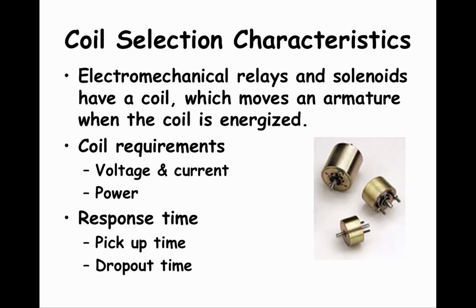Response time describes how much time it takes for the relay to actually respond once the control signal is sent to engage. Again, with electromechanical relays, large ones may have a substantial delay between when the control signal says engage and when the relay actually engages. Similarly, there may be a delay between when the control signal says to disengage and when the coil and relay actually are disengaged, or drop out.